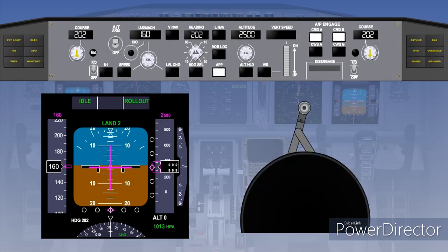If the aircraft has rollout mode, then either shortly before or at the touchdown point, localizer mode will disengage and rollout will become the engaged mode in roll. Rollout control will now use the localizer deviation signal to feed steering commands into the rudder to keep the aircraft on the centerline. There may also be an interconnection between the rudder pedals and the nose wheel steering after the touchdown, which will allow a limited authority of the steering.